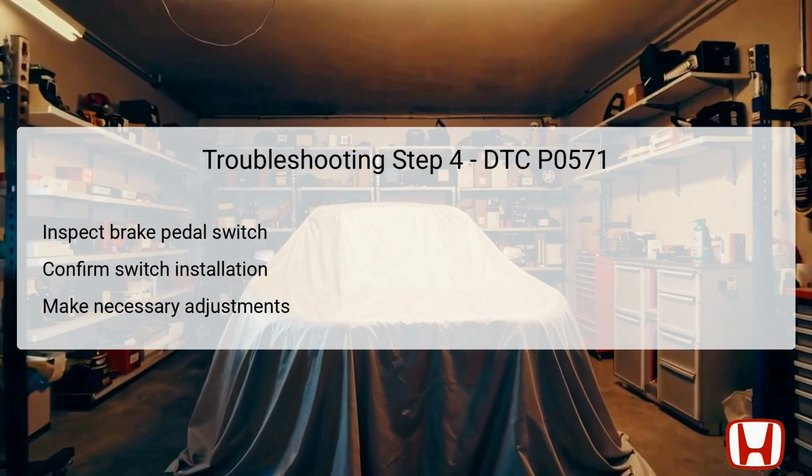Once ensured that the switch is properly positioned, conduct additional inspections to evaluate its functionality. It is essential to confirm that the switch activates and deactivates correctly when the brake pedal is pressed and released. Failing this inspection indicates that the brake pedal position switch needs replacing. Proper handling in this phase is vital to ensure that the switch operates effectively, directly influencing vehicle safety.